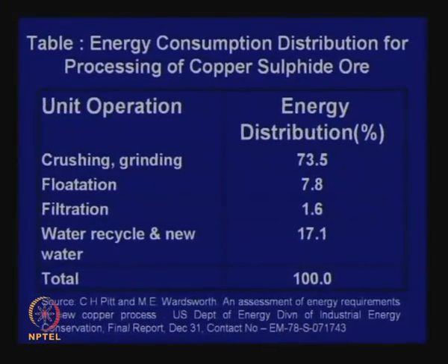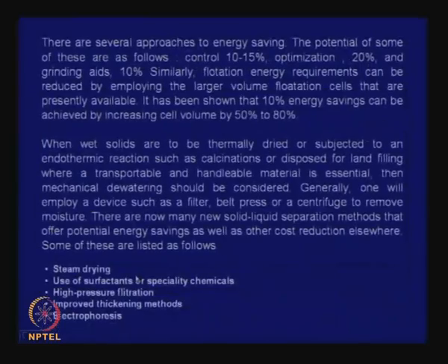Energy consumption, energy distribution, for that consumed for copper production, I have shown. And again I want to emphasize that crushing and grinding takes an enormous amount of energy, 73.5% of the energy is going into crushing and grinding, a little less for flotation and filtration. And so, whenever there is crushing or grinding involved, you have to be very cautious.